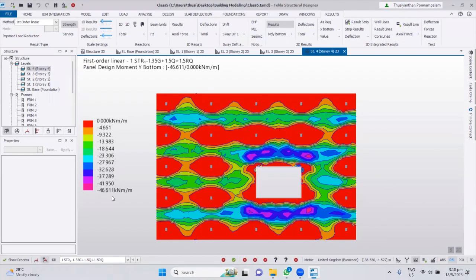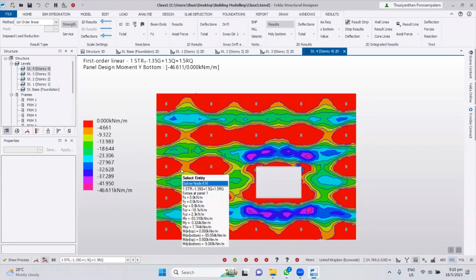Normally when you do slab design, what you want to do first is calculate the minimum required rebar, 0.13 or 0.15%. You have to calculate that first. Later, you calculate the maximum rebar you want and find out the location, which area I want the maximum. See here, only this area I want the maximum. These areas I don't need maximum. So you can identify certain areas, let's say 27 or 30 and 46, and do the calculations.